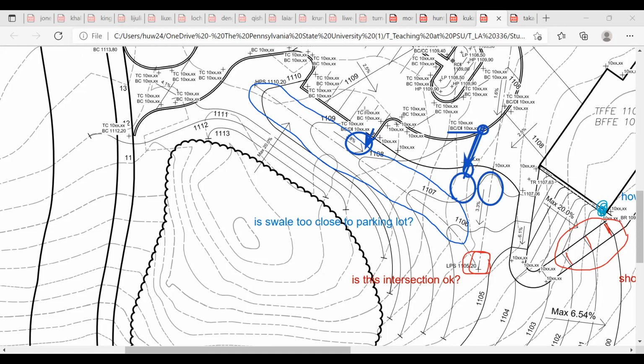Bioretention capturing from the plaza in the middle of my swale there. So do my low point and high point still remain the same, even if it's right in the middle of the swale there? You would stop your line right there. That's where you stop your center line. And you only need the spots over here. And then you design this according to the standard RDI, LP, and HP. Is that what you're trying to figure out?